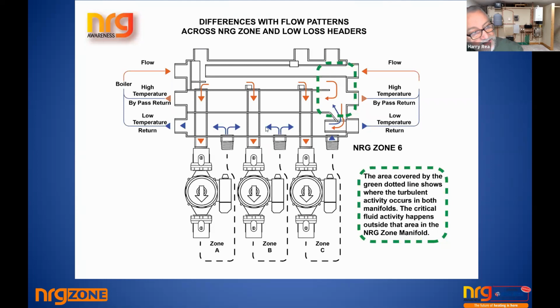So if you ever find that heat's drifting back up here, you know your boiler pump is too small. If your boiler pump is too small, you'll feel the heat drifting up here. If you have a thermal imaging camera, you'll see it immediately. In fact, there's a video online where one of these is being commissioned, and you can see it directly. The water's traveling the wrong direction and going up and feeding into the top chamber. So you can see now, people say it's just a low loss header. No, it's not.